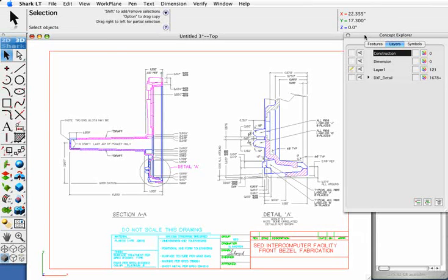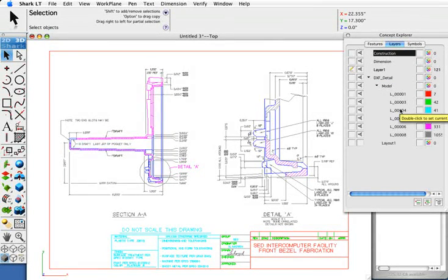For those with AutoCAD, you'll find some familiar features, including the ability to set the work layer, set the visibility, rename a layer, add a layer, lock a layer, provide a color override. In fact, in this case, the DWG file has some color overrides in it that you see are preserved when we read the file in. To change a color override, click on the color swatch. It will toggle through, or you can remove any override associated with it.